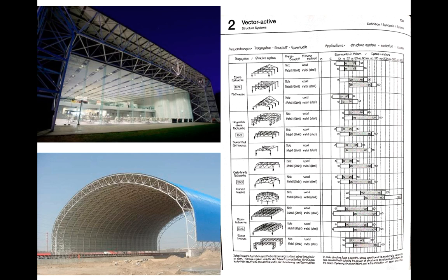So you see here we've got truss systems that can go from 6 or 7 meters all the way up to 300 or 400 meters when we're talking about trusses that are bent around an arch shape and then rotated around to hybridize both the truss with the arch section and then the double curvature of a dome. And the more we hybridize and layer these together, the greater the efficiencies we get, the longer we can span.